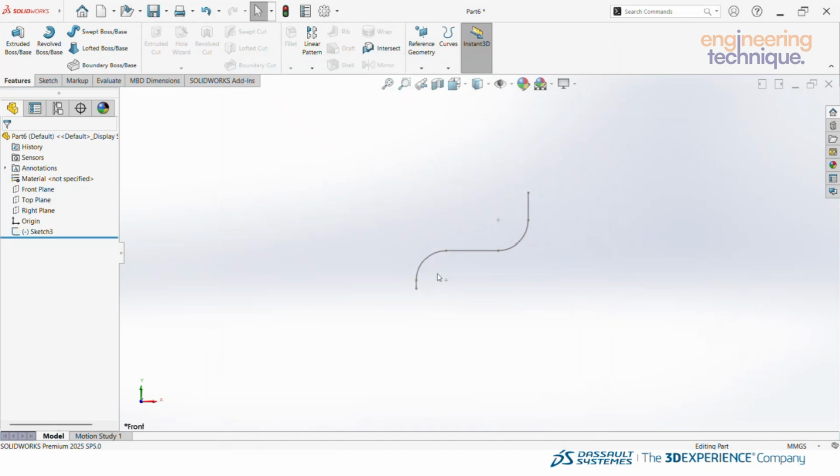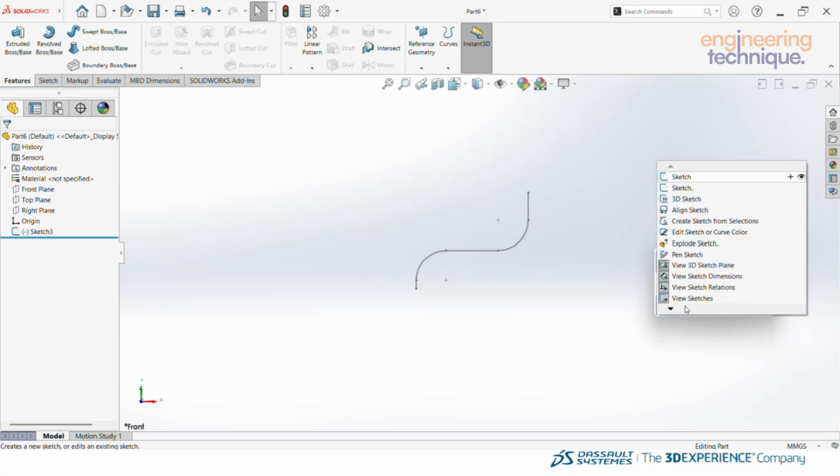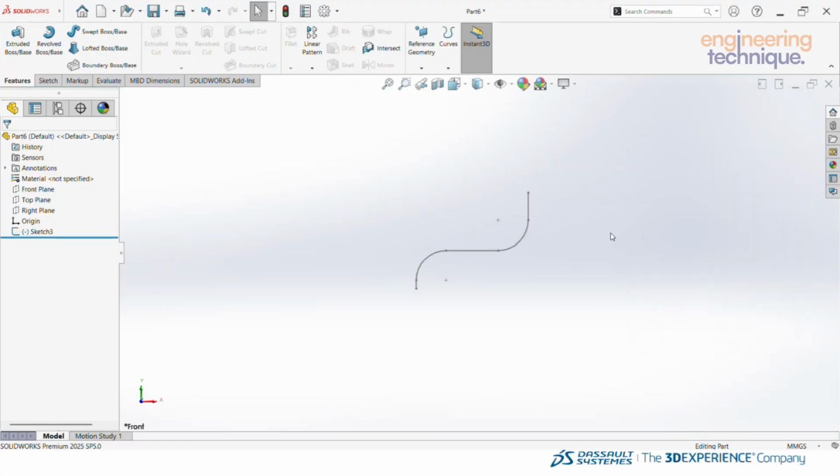If we want to directly access that shortcut bar, we just need to press S, and you can see that the shortcut bar is open. And here you can also search for a specific command. For example, if I type sketch, it opens the sketch option and all the options associated with sketch, so it is at your fingertips. We just need to press S, and that option opens.